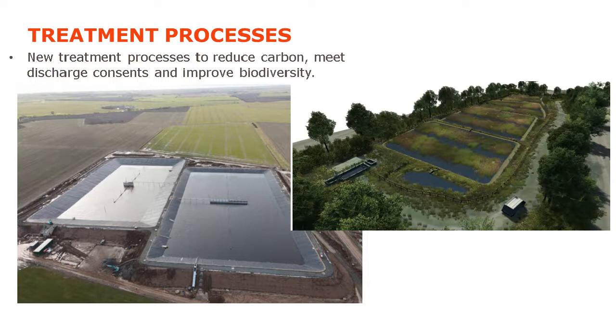It's then piped through to the second lagoon on the left, where it goes through some more biological treatment in the form of the diffusers and the aerovac units with the paddle aerator systems, as I mentioned earlier. It leaves the site from the bottom left-hand side where there are some screens, and it's then either pumped or gravity fed to the long sea outfall, depending on whether the sea is in or out as to whether the pumps are required or not.